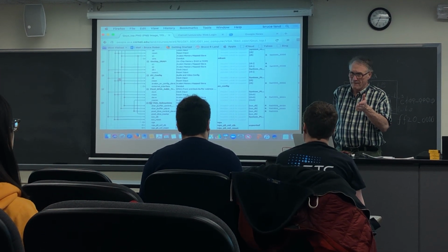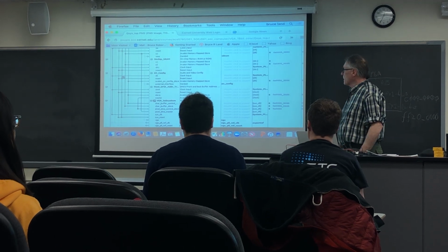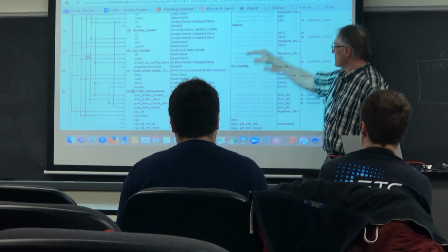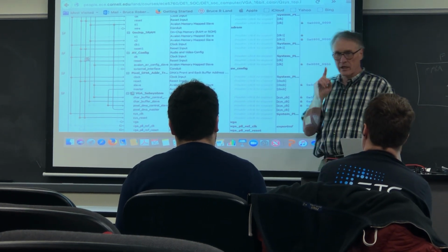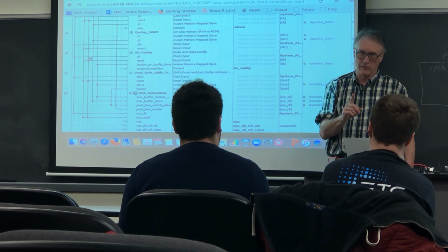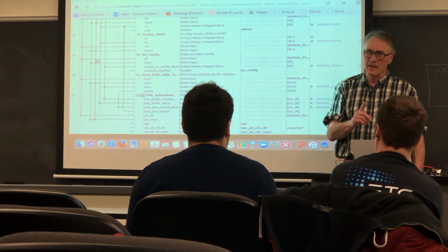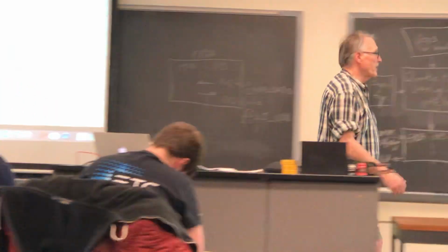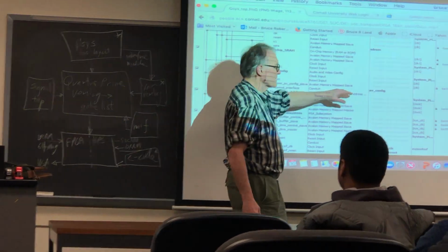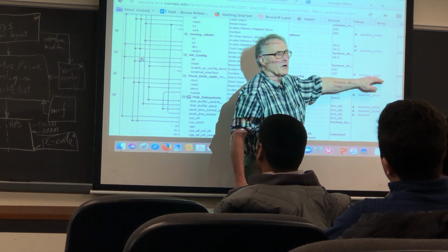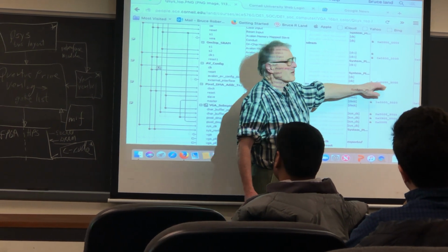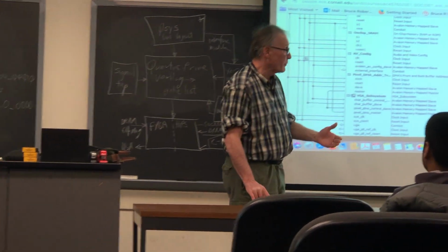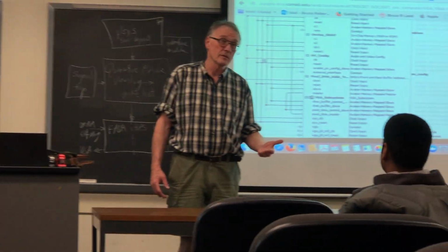Can you repeat that last sentence one more time? What doesn't overlap? Every address specified over here on a given master must be unique and cannot overlap. Addresses on different masters have no relationship to each other, and therefore the AV config address, which is in the numerical range of the SDRAM, does not overlap with it because it's on a separate master bus.